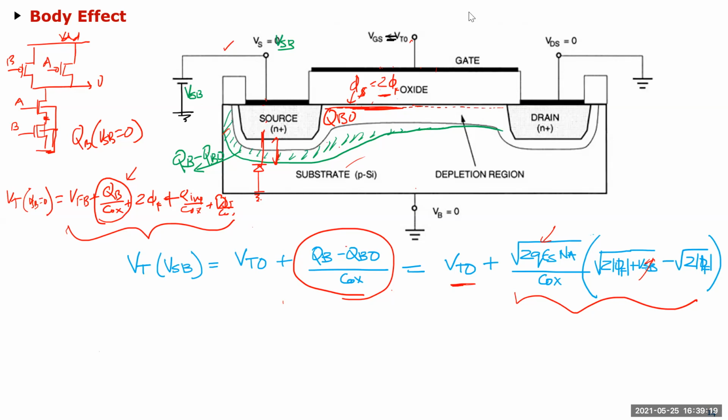But the downside of tying something like this, let's say, for example, in this case, you say, no, I can't afford to have a different VT. So I'll just draw the series device here. So what you do is you tie this. Now in a LOCOS process, you can't do this because that'll short your ground to this voltage. But in twin tub, or deep N-well process, you can do this. So if you do that, now all the source bulks are shorted for those regions.